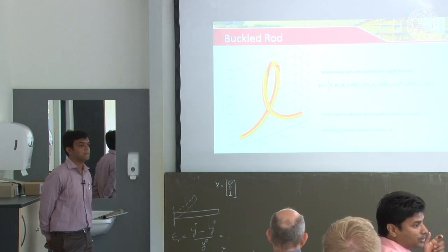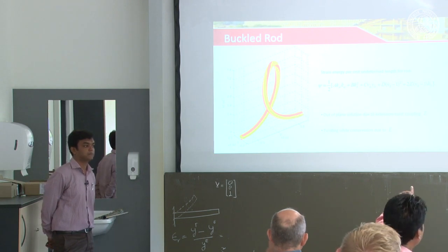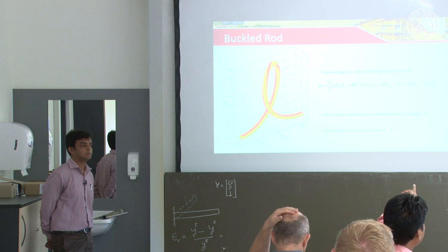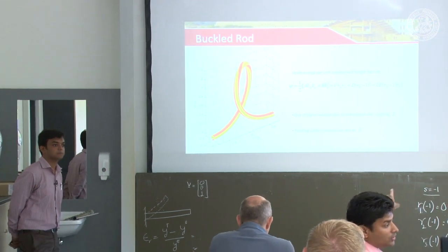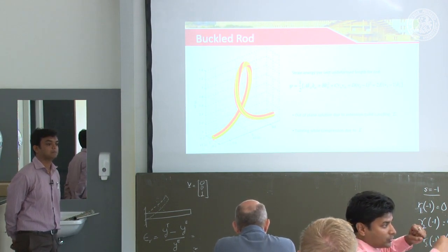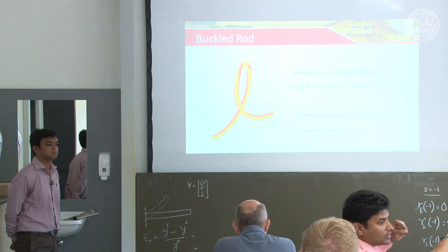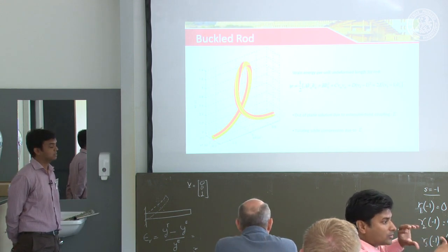And for such beams, the energy form has an extra term, 2E times (u3 minus 1) into k3. So you see, because it has this intrinsic twist in it, if you try to stretch such beams, it will also automatically twist.